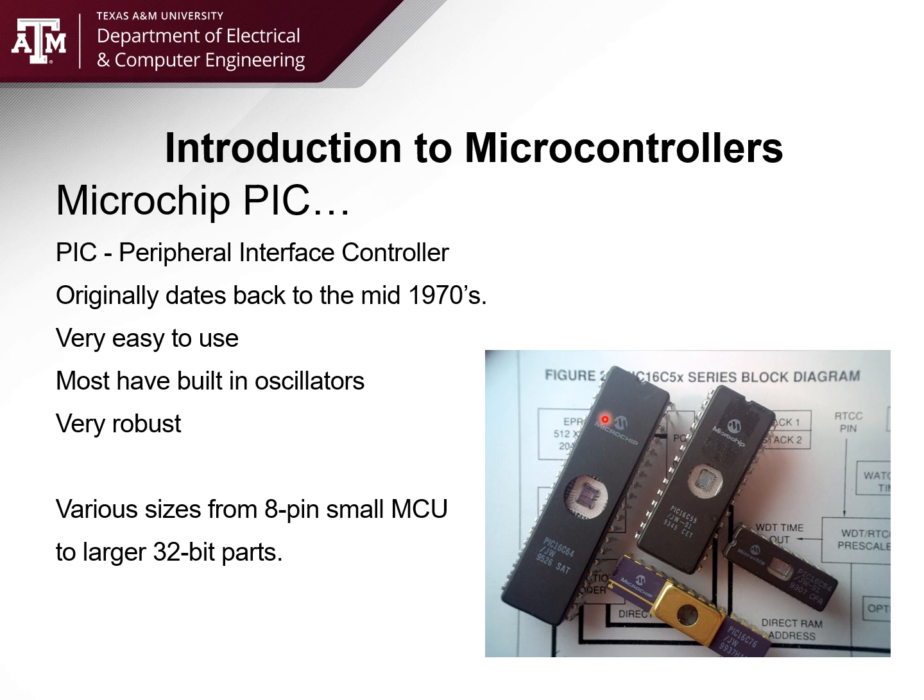Typically, I can have system applications returned from the field damaged for whatever reason, usually lightning. The processing solution is usually still fine. Usually some other circuit gets damaged. Microchip PICs are very, very capable. They have everything, again, from the 8-pin package all the way to larger 32-bit systems. Very fast, very full of peripherals.